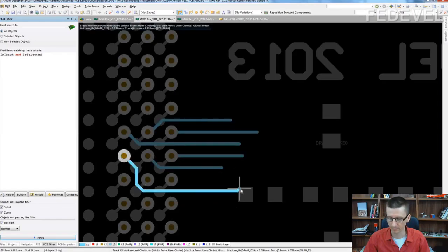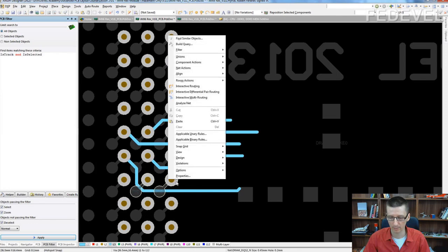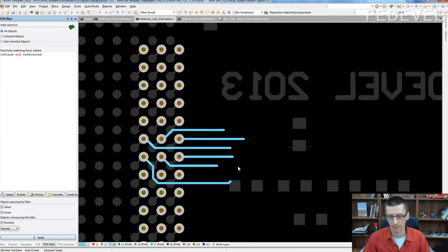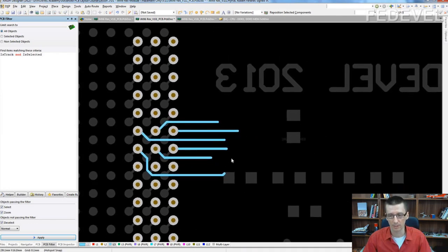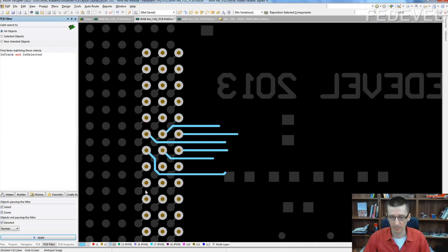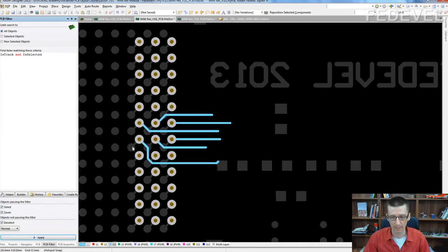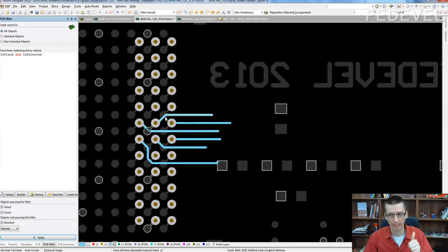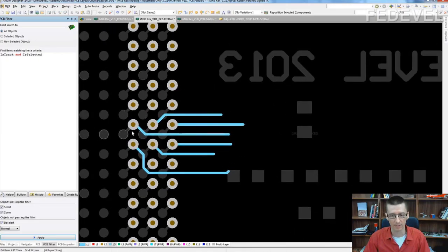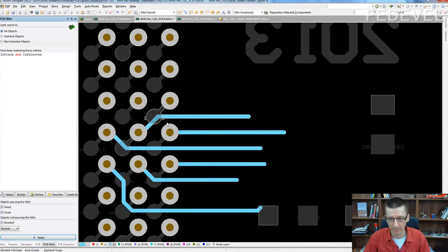This way, this one is blocked now, here. What is even worse is that if vias are placed this way, not only is layer 3 blocked, all the layers are blocked. In all the layers, you can only draw one track between these vias. And this is the main problem. That's the reason why we cannot fan out this third column, because between these vias we can only draw one track.